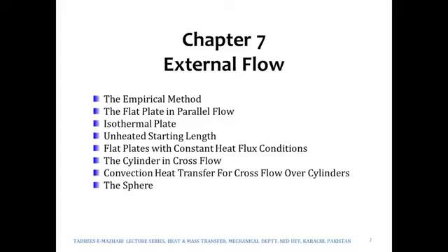So it would depend upon the temperatures of the surface and the fluid, the conductivity of the fluid, the velocity of the fluid, the specific heats, and others as well. So therefore, a major problem that we usually come across in convection is to find out the convection coefficient.